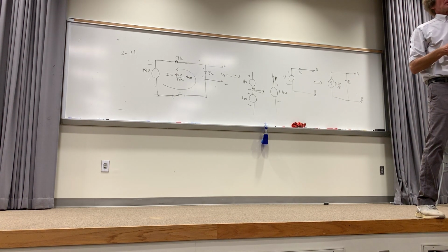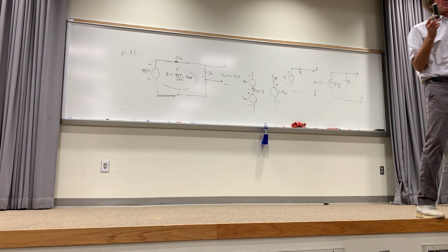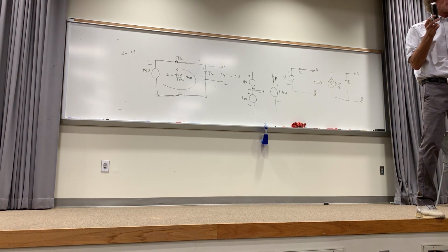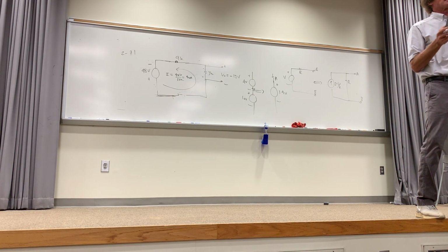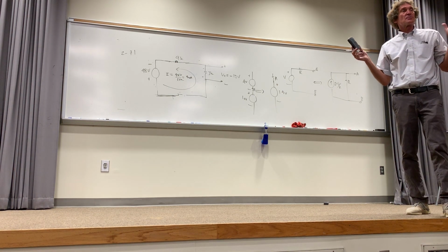Yes. Really, the addition of current sources is key, and also being able to start with the one that you can actually start simplifying from. In other words, dead center in the middle. I can take that and make it a current source and take the 2 parallel current sources and combine them.